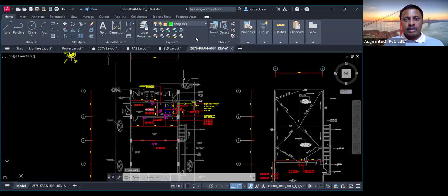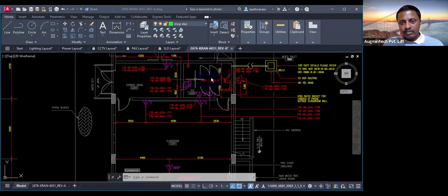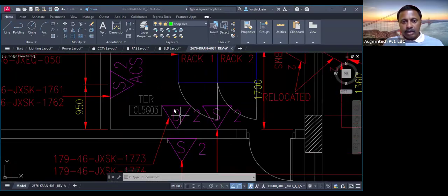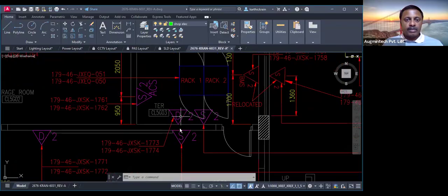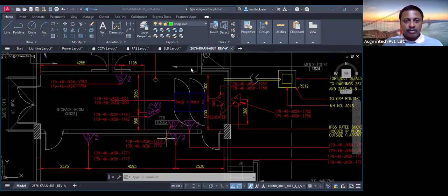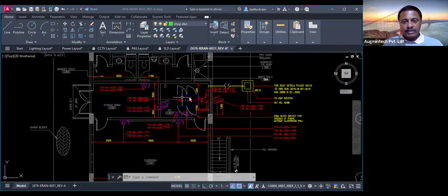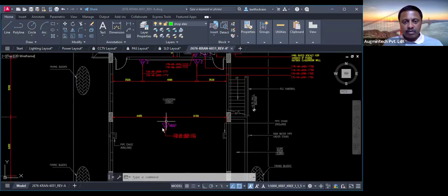The data or voice in the sense as you're seeing it over here. So this is that point. We have a telecommunications rack over here, and these are the data voice points. These are the outlets. From here we connect Cat 5 or Cat 6 cables, and they are terminated in the patch panels or in these racks actually.